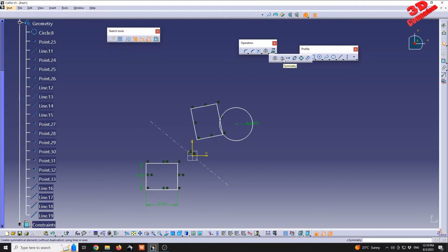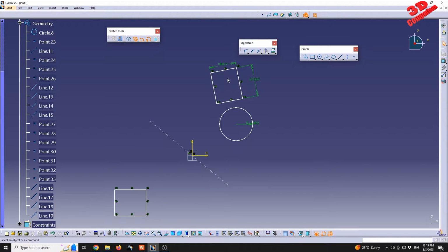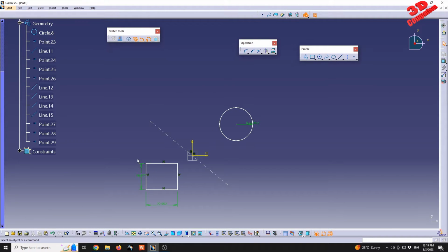But for some reason, symmetry for the same element around that will move it over here. Now we see that if I applied it again, it managed to update that, and we have the newly updated position. So I've noticed that symmetry in some cases is a little bit buggy, depending on your selection. I mostly intend to use mirror and afterwards just delete the other side if not needed. Maybe this is only specific to my CATIA version.